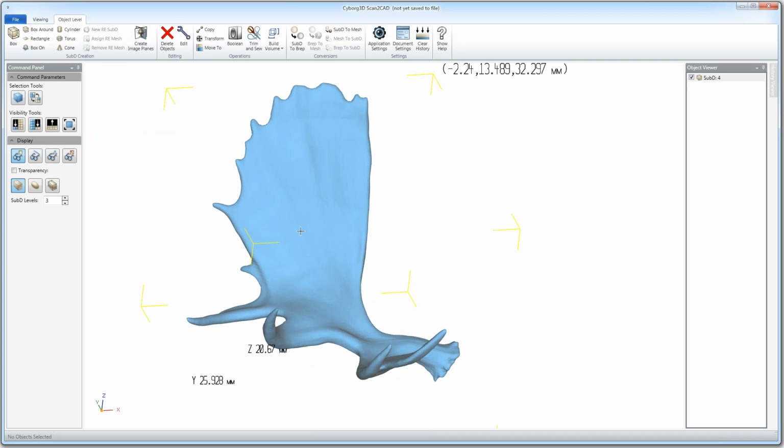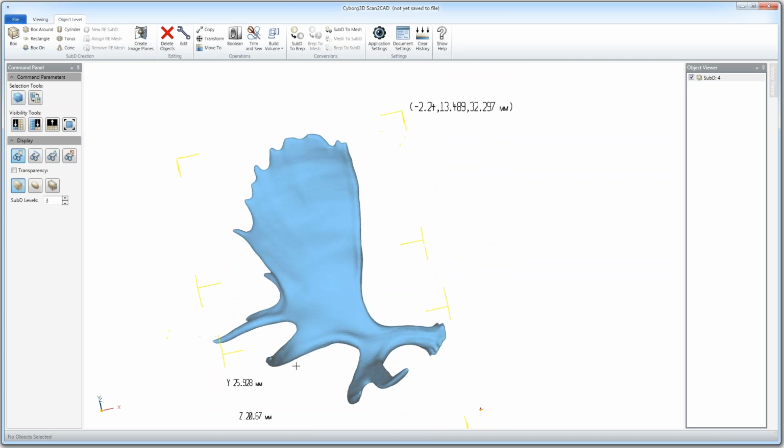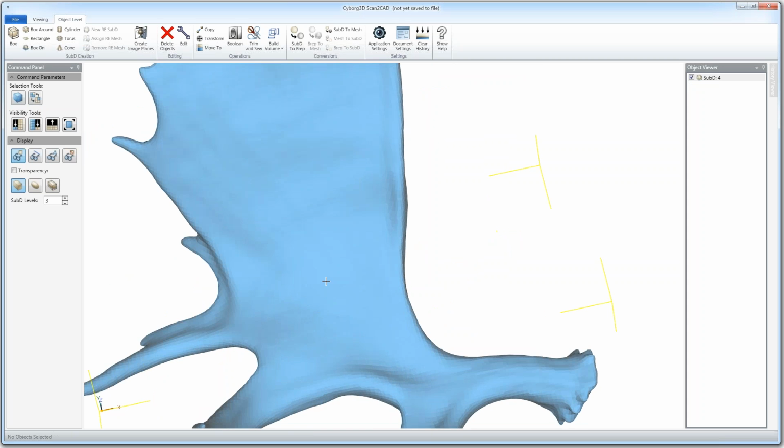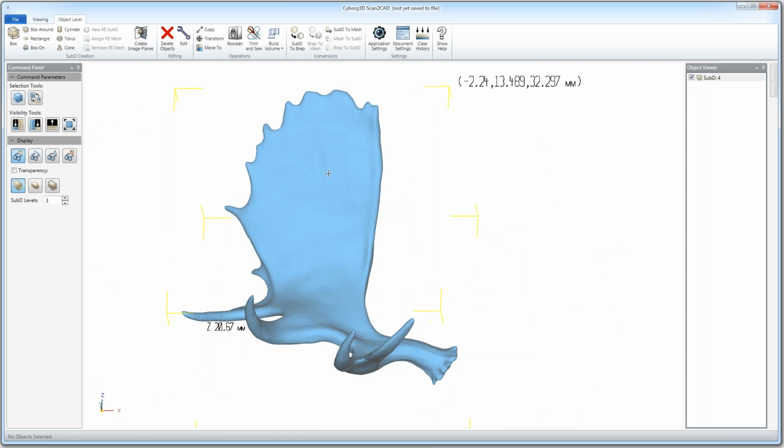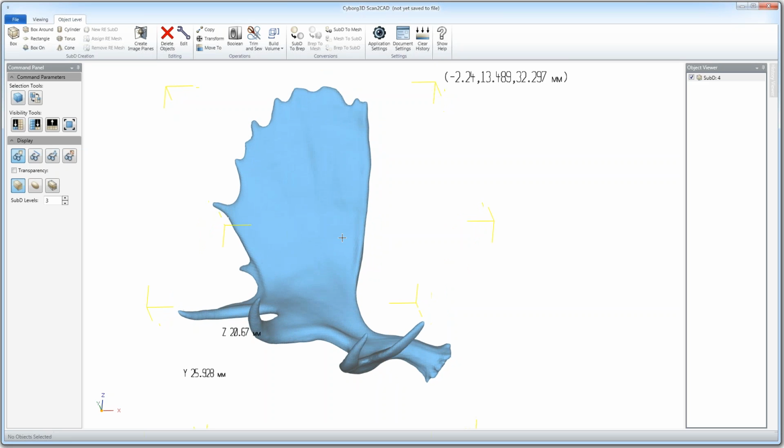Takes a little bit longer, but now you can see that we've captured some of this fine detail in here on the mesh, some of these veins. We can go a little bit finer, but it does take a little bit longer. So for quick demo purposes, we're not going to do that. I've actually run this at 0.02 and 0.01, and you basically can't tell the difference when you're looking at the quad wrap mesh versus the actual original scanned mesh.